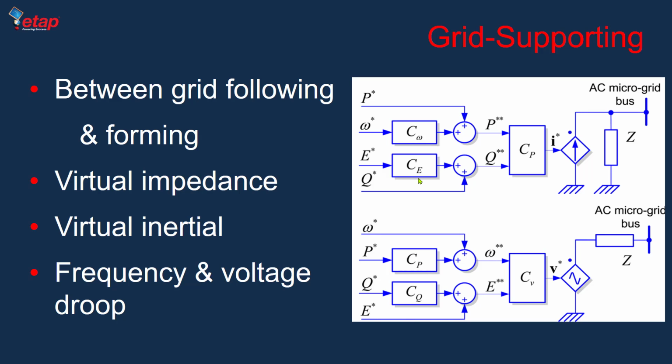So when it comes to wind farms or solar farms with energy storage, there are lots of reactive power resources available. To make sure there is coordination and a contribution from all of them without a fight, there's always a droop, let's say, for the reactive power. We'll look at more details in the next few slides. But you can create a grid supporting unit out of grid following or out of grid forming. Very similar, both of them support, but if you lose the grid, you cannot function as a grid supporting following unit. With grid forming, you can still support.